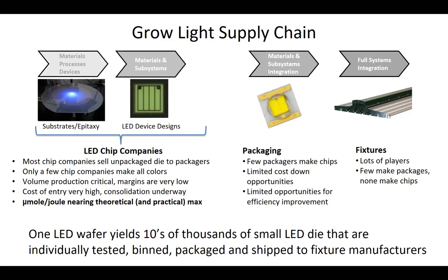And there, the mean time to failure really depends on the quality of manufacturing. I've had solid state lighting fixtures that we've installed here at RPI that have been on 24/7 for 10 years and a very, very low failure rate. I've had other ones that fail within a couple of weeks, usually because of a solder joint.